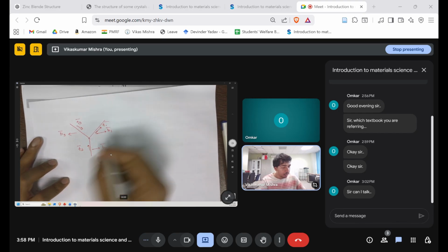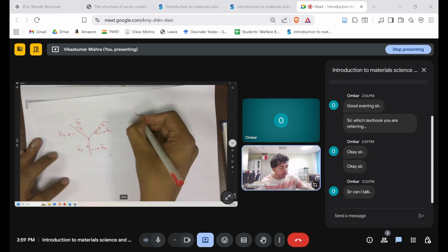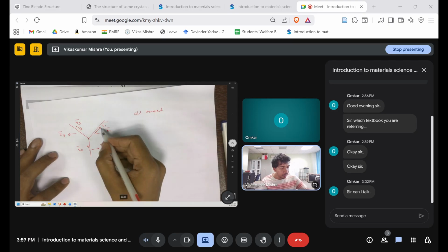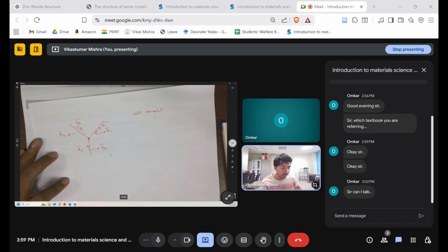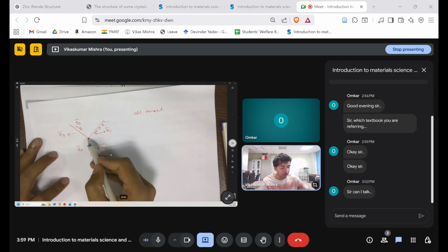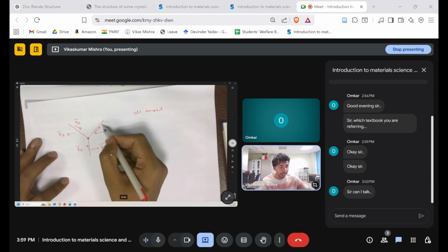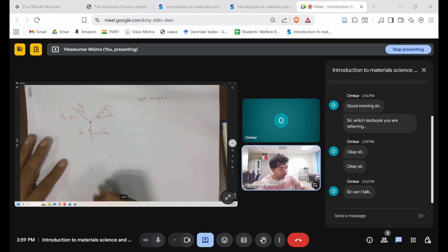Okay. So at the node, the first condition is that all tangent vectors should either be towards this particular node, or they should be away from the node. So see, this one is going away from, this one is coming towards, this one is coming towards. So what do we have to do? Two are coming towards, so let's change this direction. What changes will we make over here?